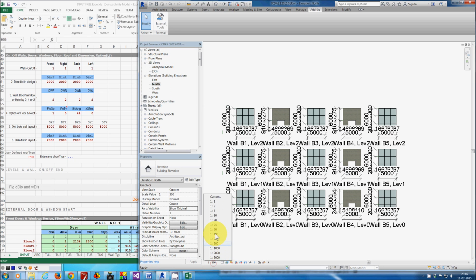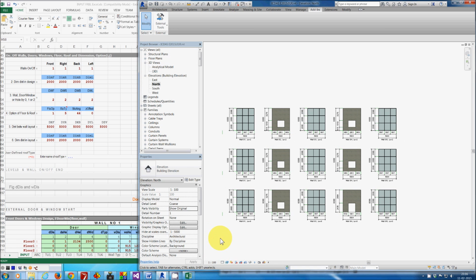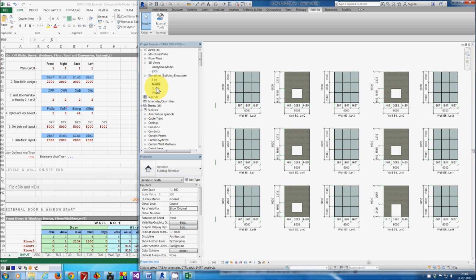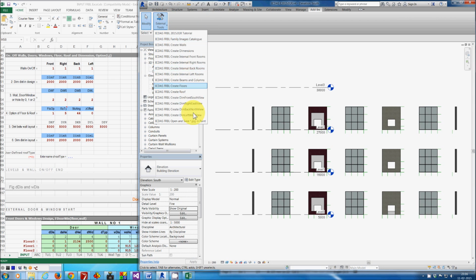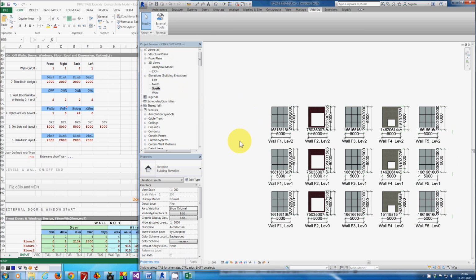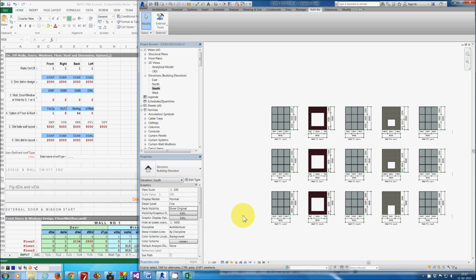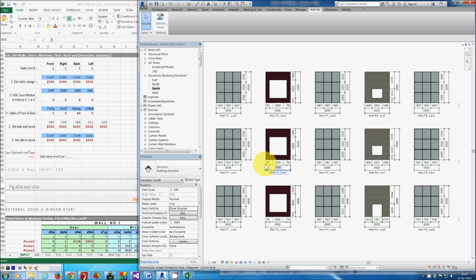It's set to be in 100 scale, and the south view, and I create dimension for the south view, 100. So you have the distance to the start of the hole in horizontal and also vertical direction.